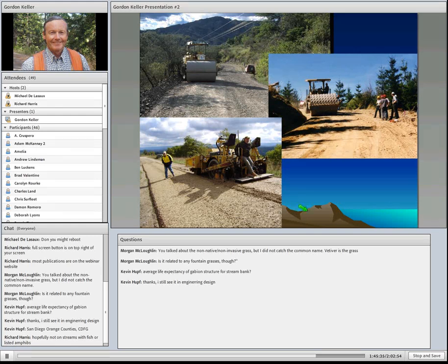This picture down here using a paver putting down aggregate was, this is back at Penn State and their Center for Dirt and Gravel Roads, which is doing a lot of good research these days on gravel roads and low volume roads. They use it for both maintaining good depth control and initial compaction, then come back and requires a little less compaction later on. But either way, these are all examples of compaction, and we often don't compact aggregate that we put down on roads, but to me it's very cost effective to do it.